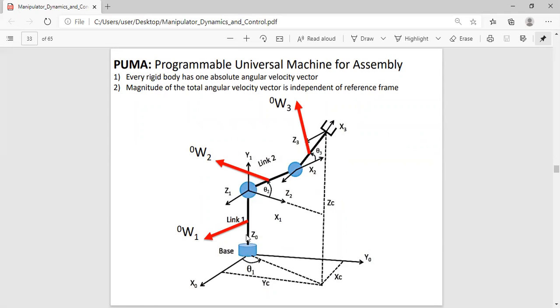The z is the axis of actuation. It defines the direction of my velocity. More importantly, when we have a serial manipulator, the velocities are adding up, especially, for example, in θ2 and θ3, because the velocities are relative, correct?